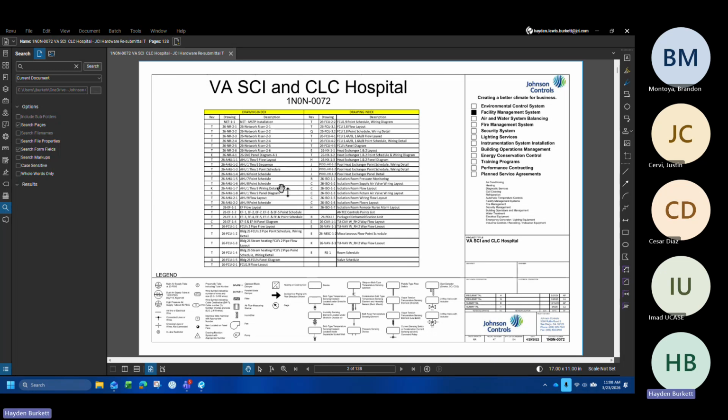We go over some basic wiring detail. We have a panel diagram. Then we get a separate exception for air handler 9 because this is a dedicated outside air system. Then we go over all of the variations of exhaust fans and their associated interlocked systems. Same thing, you'll get a panel diagram.